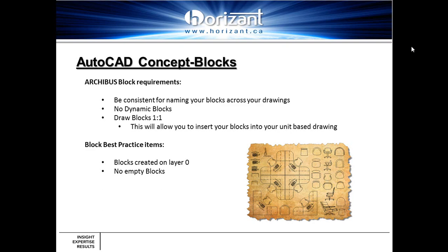The other item we want to do is make sure we have no empty blocks. It's more of a drawing practice, just to make sure that you don't insert a block that has nothing inside of it and therefore have an object inside your drawing that is empty. It's just a rule of thumb. Or if you have a block, don't go in and alter the block and remove all the objects, but leave the block inside of there. So just a knowledge-based item.